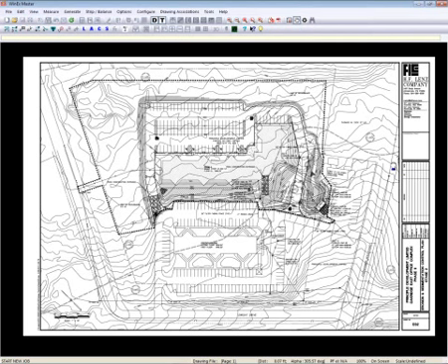Unlike many software providers in this market who use what's called the TIN network, which stands for triangular irregular network, and is a series of triangles spread all over your drawing, they, for the most part, can only give you the elevations where the vertices, or the points of the triangles, touch another triangle. And those triangles are fat and skinny, tall and short. So they're limited as to where they can pull elevations from and how often they can pull it throughout the drawing.